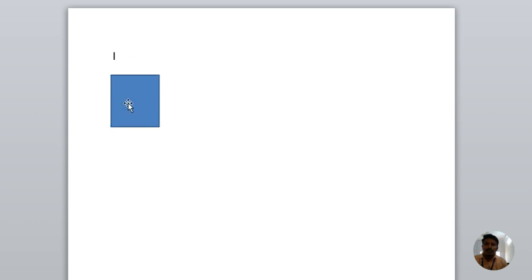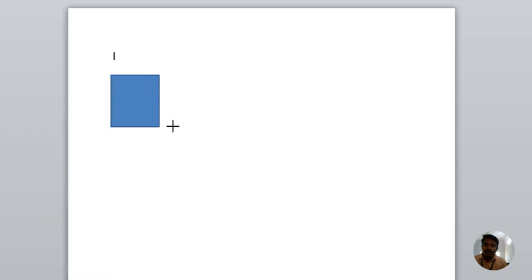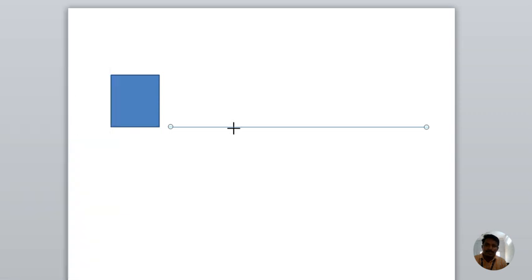It is the orthographic view, 40 mm each side of the square. First of all, I am taking the reference line, the XY line. Here put 30 degrees to each side. For example, the points are A, B, C and D.